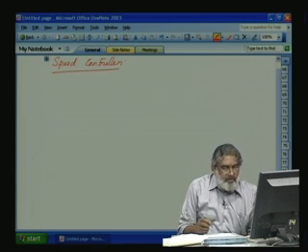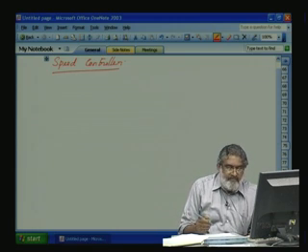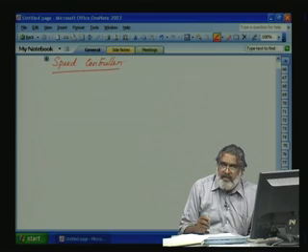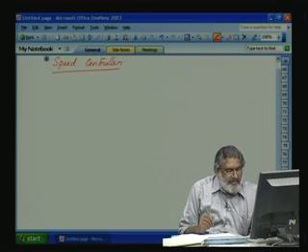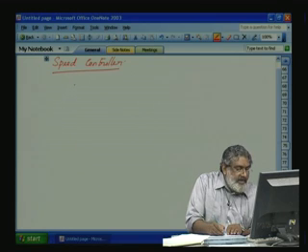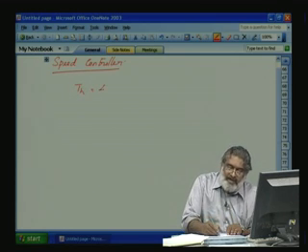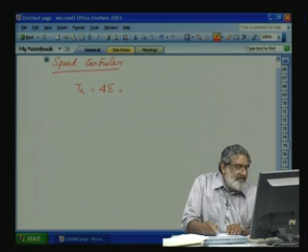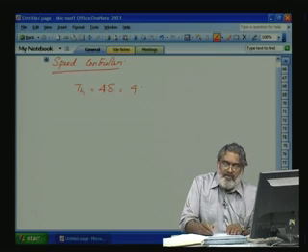The speed control also we can realize in the same way we have realized the current controller. So the reference voltage here, speed reference, we will always limit between plus 10 and minus 10. The Tn is equal to 4 delta, that is equal to 4 into 2 sigma plus T1.